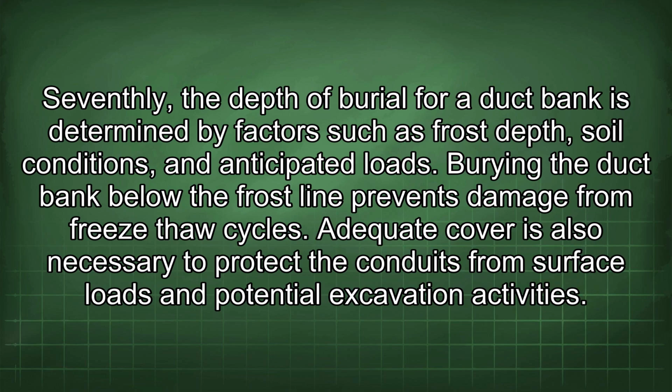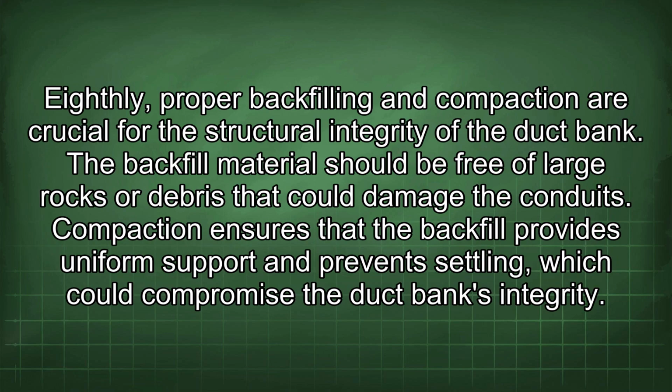Thermal modeling may be necessary to determine the appropriate conduit spacing, concrete mix, and backfill materials to manage heat dissipation effectively. Seventhly, the depth of burial for a duct bank is determined by factors such as frost depth, soil conditions, and anticipated loads. Burying the duct bank below the frost line prevents damage from freeze-thaw cycles. Adequate cover is also necessary to protect the conduits from surface loads and potential excavation activities. Eighthly, proper backfilling and compaction are crucial for the structural integrity of the duct bank. The backfill material should be free of large rocks or debris that could damage the conduit. Compaction ensures that the backfill provides uniform support and prevents settling, which could compromise the duct bank's integrity.